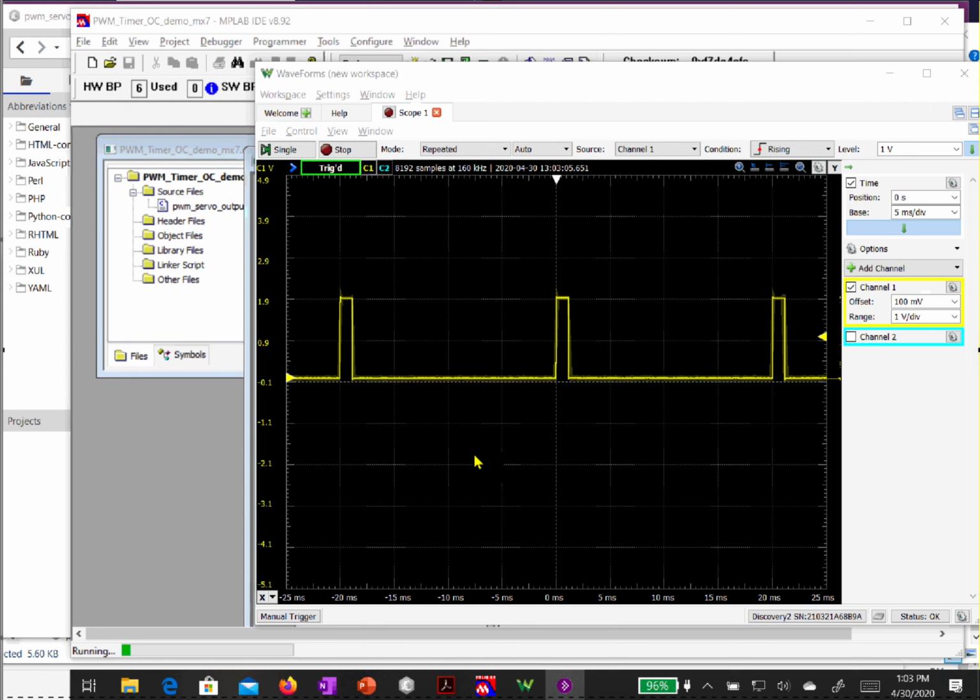You can operate more than 8. So we have 1 timer for the heartbeat, the 20 millisecond, and all of them will need that. I could use 1 timer for 8 motors. I could use another timer for another 8 motors. I could do 16 motors. I would need to use 3 timers to do that, and those input signals could all be done independently. So yes.